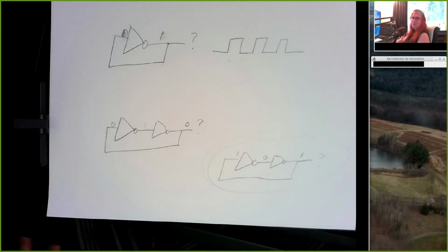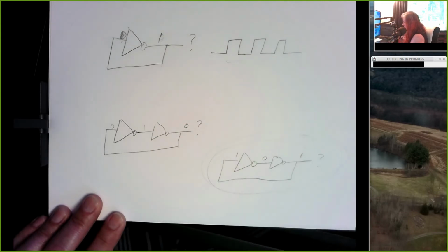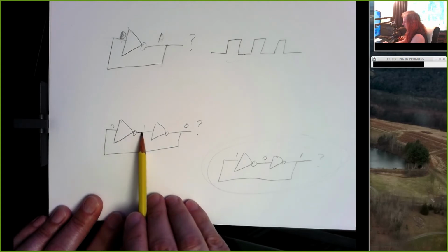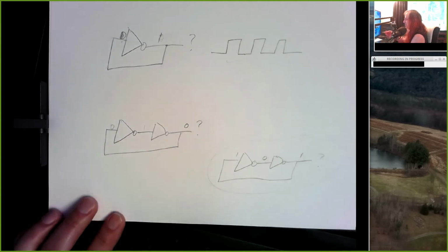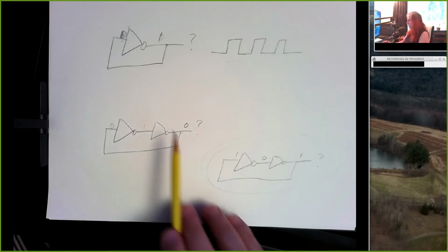And now if I take a wire, I connect it to ground, and I touch the other end of it here just for a moment, that pulls this output low. There's a 0, that gets inverted to a 1, that gets inverted to a 0. My LED will turn off. And so I could build a really kind of poorly behaved 1-bit memory just with these 2 inverters.